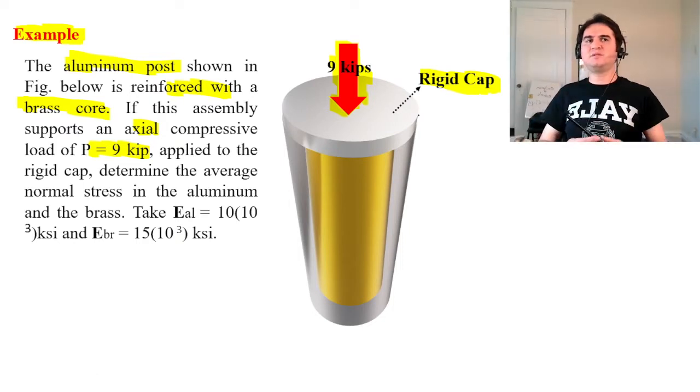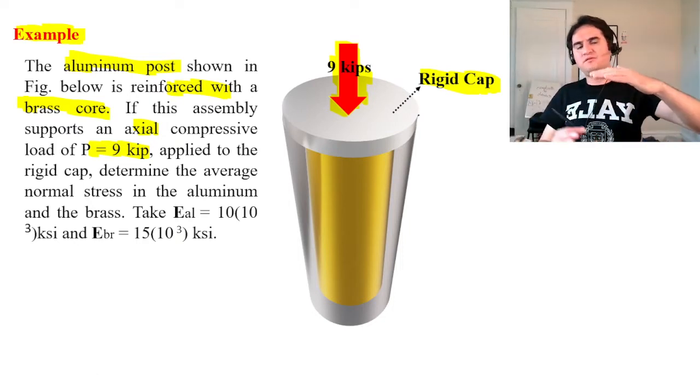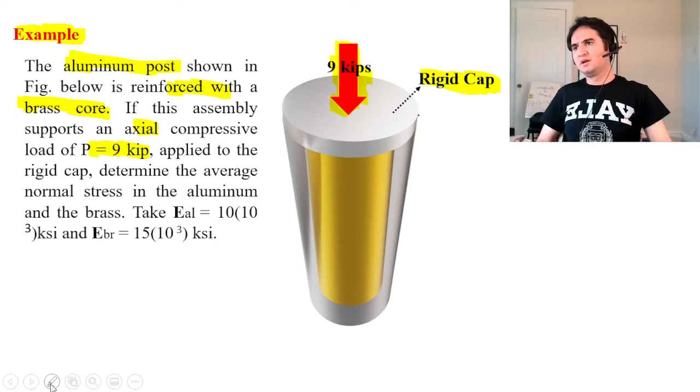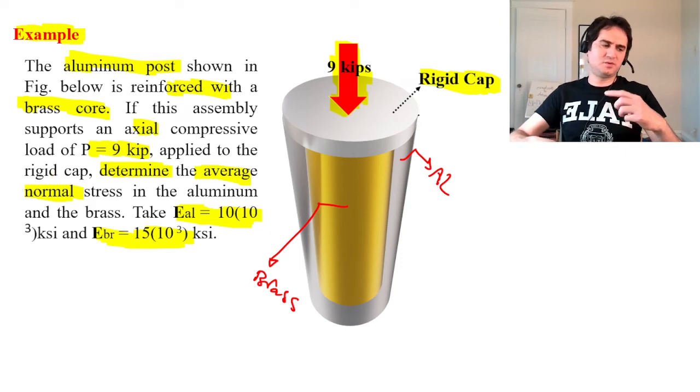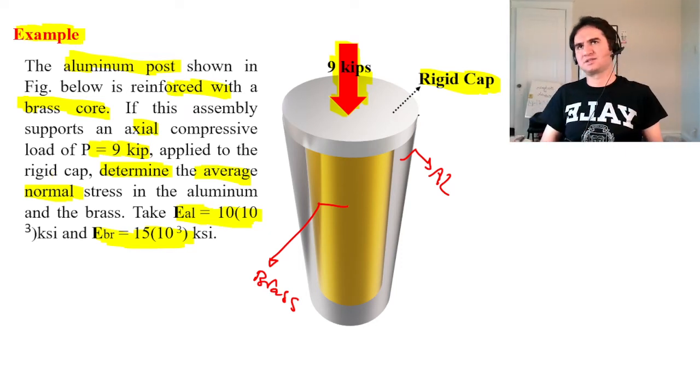This acts like a distributor of force between the two materials, the outer cylinder of aluminum and the inner core of brass. If we know the specification of each material, for which the modulus of elasticity for aluminum and brass is provided, we want to know the forces or stresses. So stress, as soon as we know the forces, force over area is a stress.